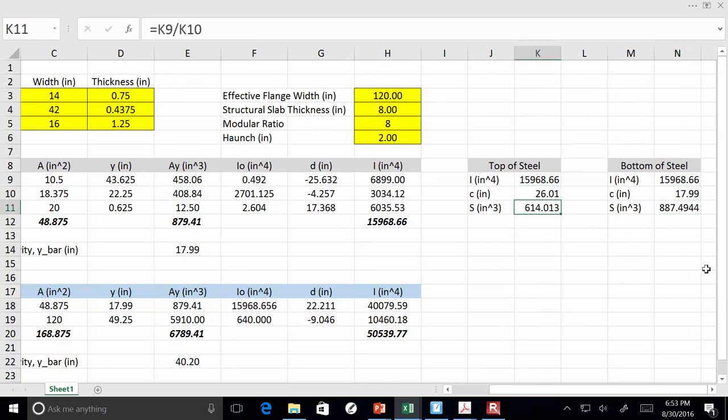All right. Make sense? And just divide those two out. So what that means from a behavioral standpoint is, looking at these section moduli, I can make some pretty straightforward assessments. Section moduli are in a way an assessment of the performance of a given section. So if I'm looking at these two section moduli, the section modulus for the bottom flange is larger. That means in turn, when I apply moments, it's going to have smaller stresses than the top flange.